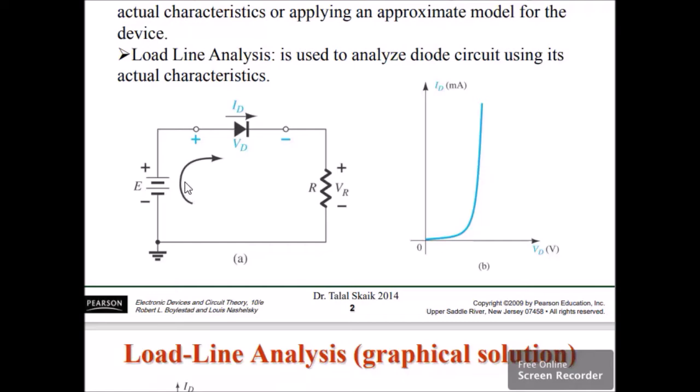That's the arrow. And then it goes to our diode. We said the diode is just like a switch which conducts in one direction. Since the current goes through here, our diode is on. It allows the current to flow. From here, there is no problem. It passes because it's in the right direction, and then it goes to our resistor and goes back again, and the circuit is complete. So, not really that there's no problem, but on this circuit, our diode is in on condition. It is on because the direction of the current is correct.